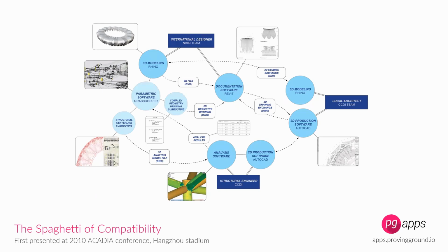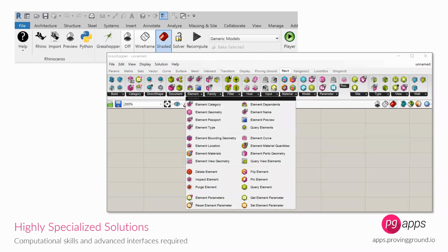And on the other side of things, we have what we would characterize as more specialized solutions, i.e. requiring certain skill sets in computational design software, or even having to code directly. And one of the more out of the box ones that's become quite popular in the last year or two has been Rhino Inside, which is an extremely powerful computational design solution that lets you launch Grasshopper through a place like Revit, and that provides you with a portal for interoperating with Revit data from Rhino. And it's quite extensible. There's many options.